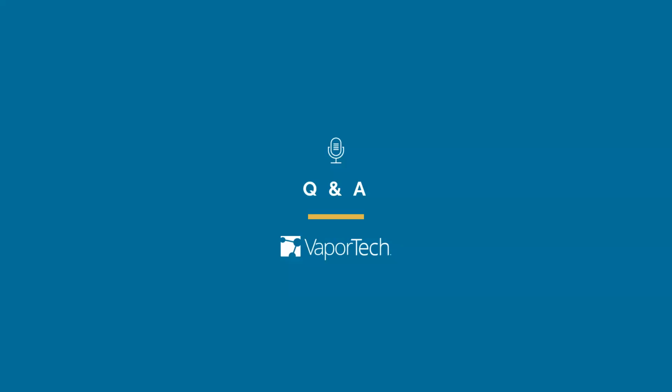Is magnetron sputtering similar to PECVD? No. Magnetron sputtering, being a PVD process, uses a solid source to create part of the coating, or the entirety of the coating. You can deposit a pure metal, or even in some cases, if you have radio frequency power supplies or different types of power supplies, you can create from a solid source that is an oxide, for instance.